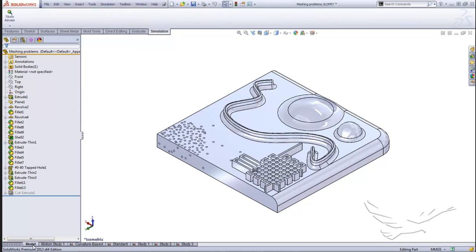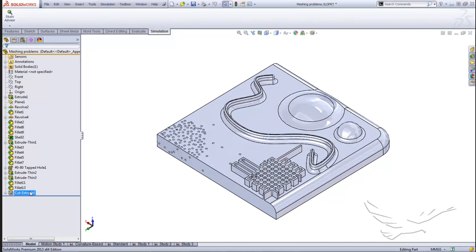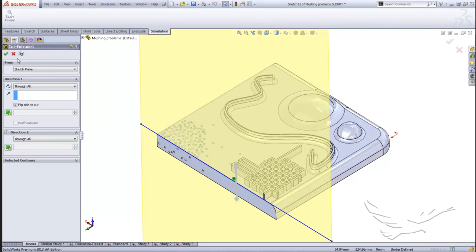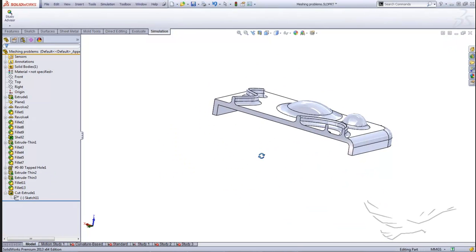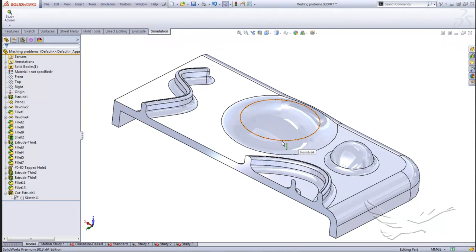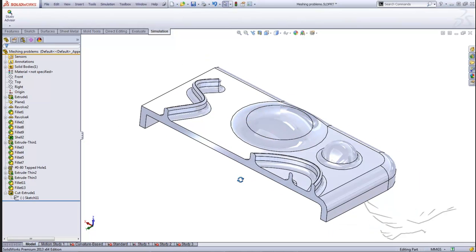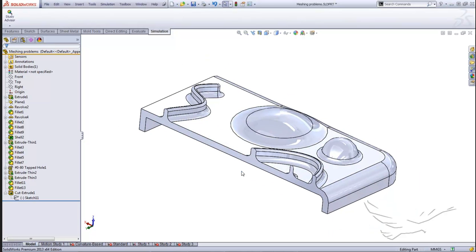Now, if you're still having issues, then there is a more aggressive approach that you can take, and that approach involves physically cutting your model, and it allows you to take a piecewise approach to the problem. So you cut your model into a third, half, or a quarter, and then you mesh from there. You mesh the quarter of the model or half the model, and you take a piecewise approach to see what element sizes work, what doesn't.